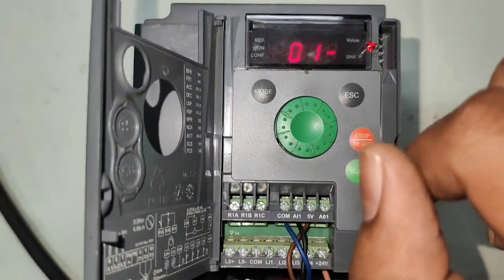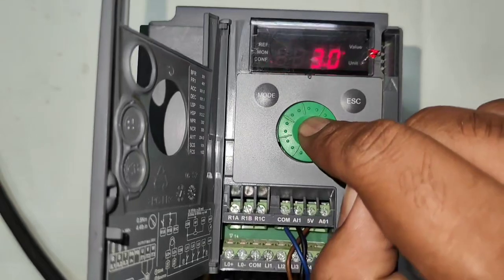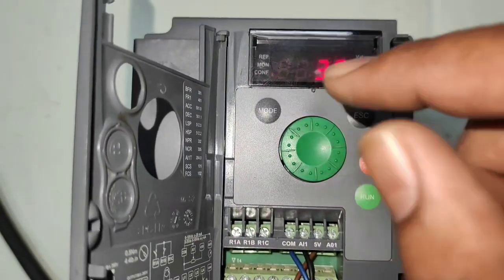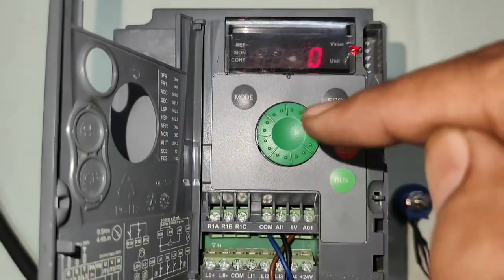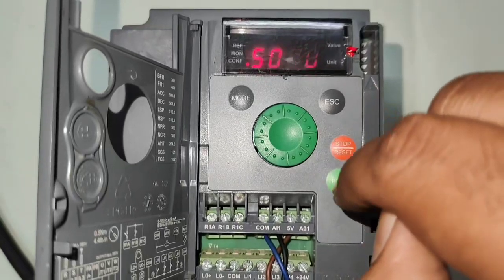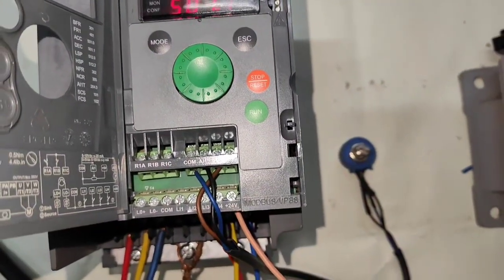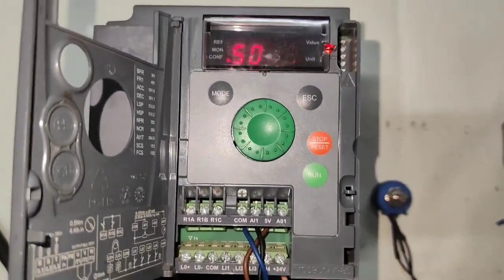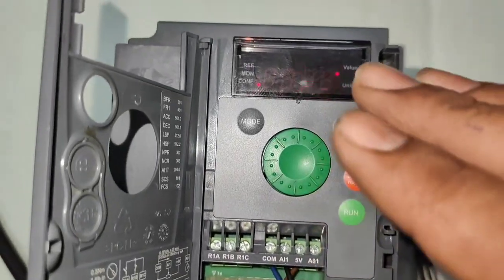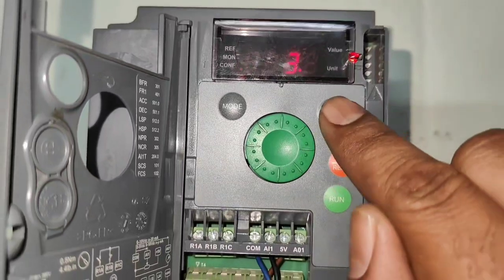And the next parameter is for acceleration, 501 group, 5010. For acceleration time we set 3 seconds when you start your drive, so in 3 seconds your drive will come to full speed. And for deceleration, parameter 501 group 1 is for deceleration when you stop the motor. From high speed to 0 speed, how much time your drive will take, so we set deceleration time to 3 seconds.